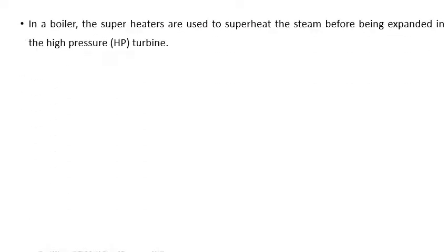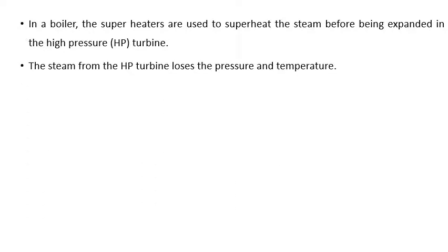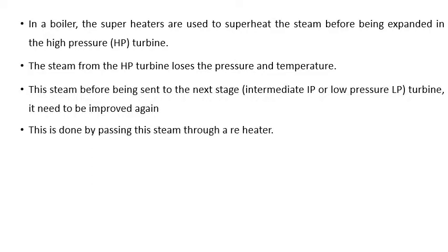In the boiler, the superheaters are used to superheat the steam before it is expanded in the HP turbine. The steam from the HP turbine loses pressure and temperature. Before being sent to the next stage, the LP turbine, it is heated again. A reheater is not always advised because it increases your cost, so it has to be justified.